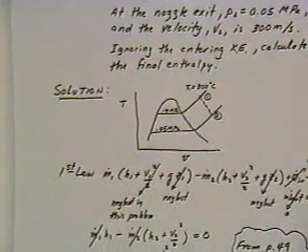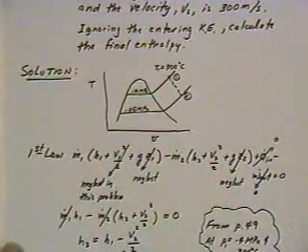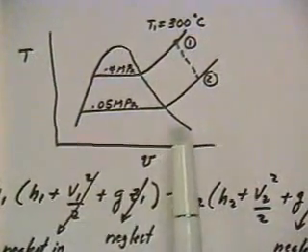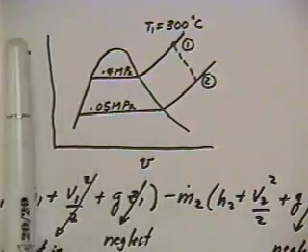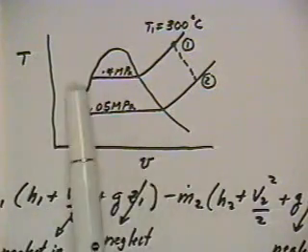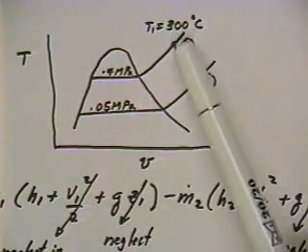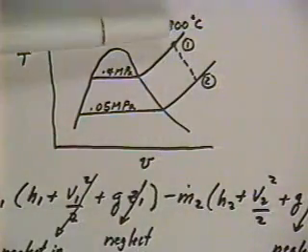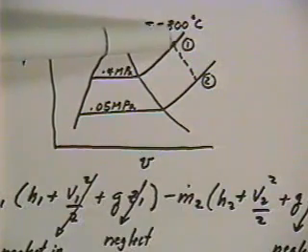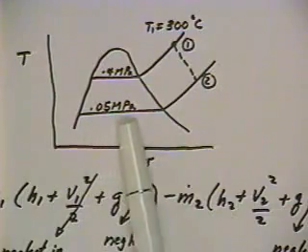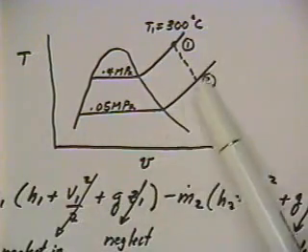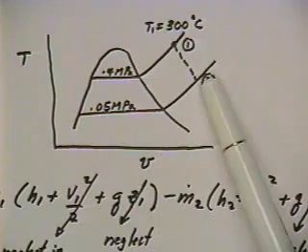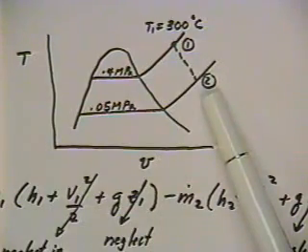Okay, so let's zoom in a little bit more on this little diagram here so that we can see exactly where we are. This is a TV diagram now. We've got 0.4 of a megapascal up to 300 degrees C, and so our entering condition at state 1 is in the superheated region, and we're expanding down to a pressure of 0.05 megapascals, so we're going to be expanding around to a little bit lower temperature as well as a significantly lower pressure.